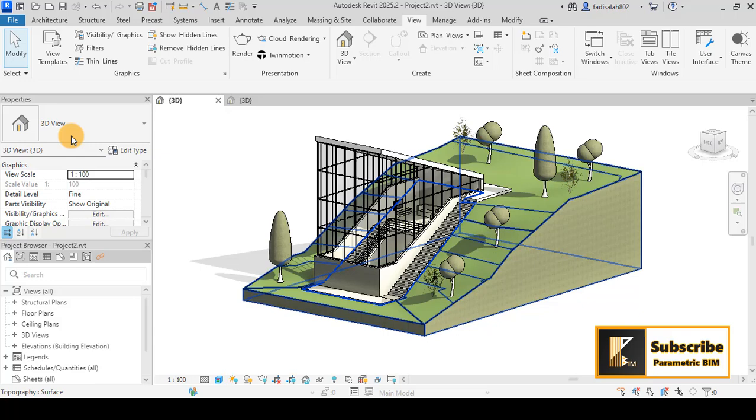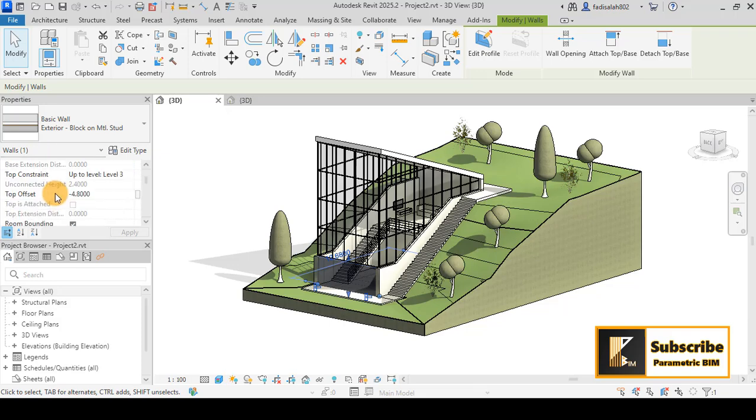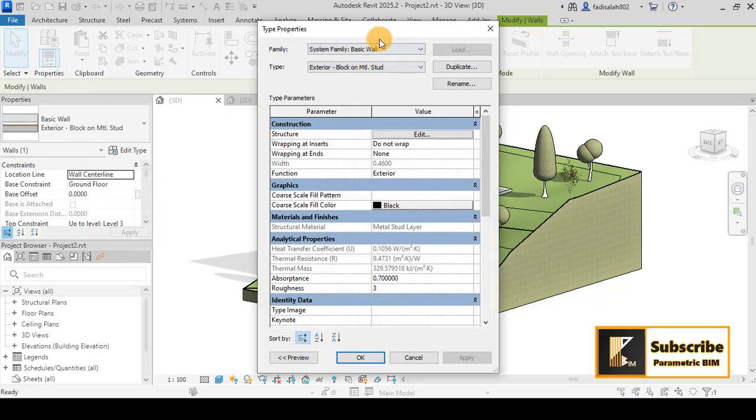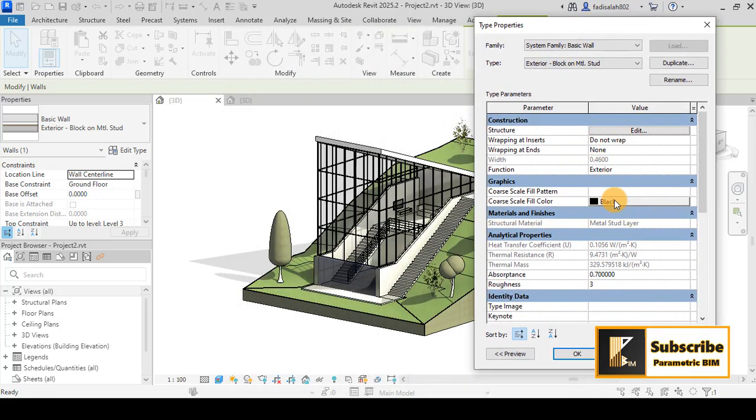And also, as you see here, we have some properties of the components that we selected, and we will go on and talk about that later. It will give you some information about the properties of the selected component here. Now let's talk about the difference between these properties and the general properties that we have in edit type. So if I select this one and go to edit type, the difference is that if I change anything here, it will change the properties of the type itself in all the project.